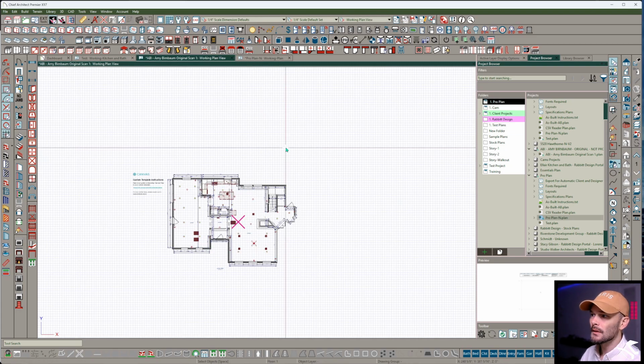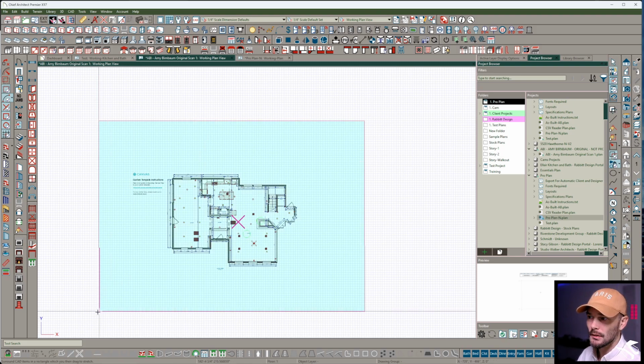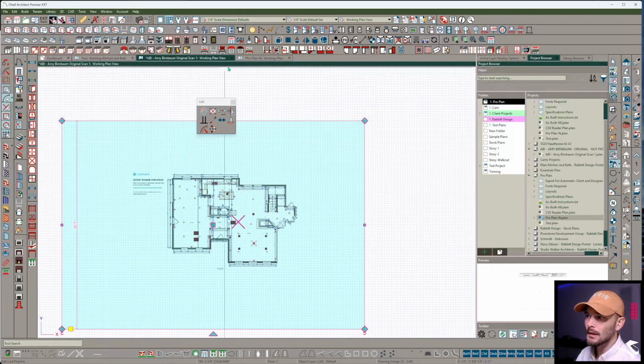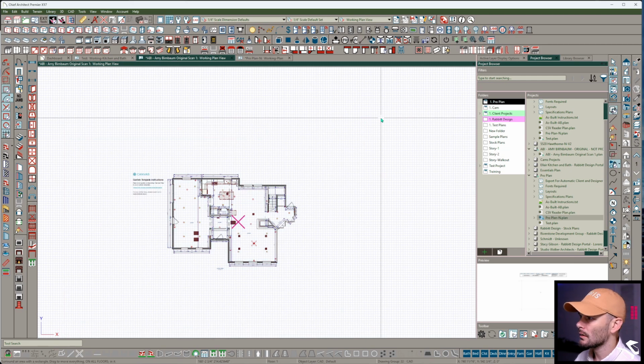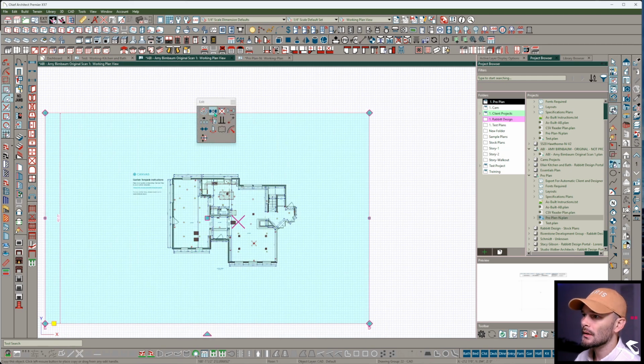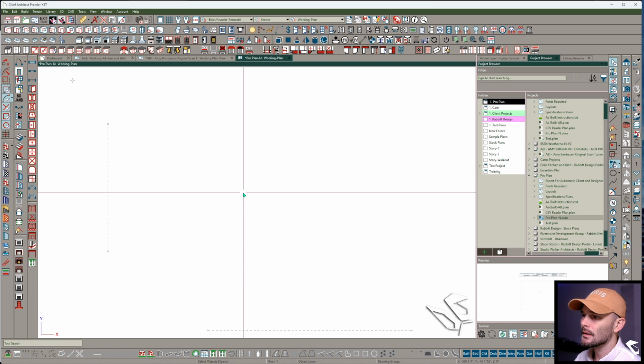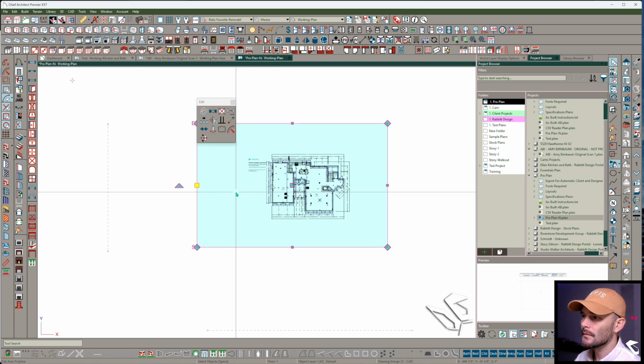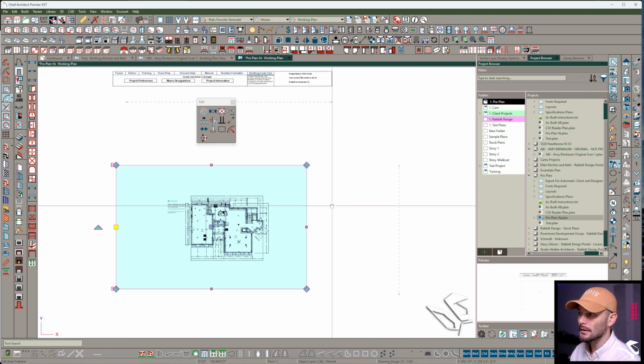Now, let's give this a shot again. I'm going to use that edit area tool, which is in the edit menu. I'll edit this, copy paste. Oops, let me try that again. Wrong tool. There we go. Copy paste, paste hold position. And notice there was no warning. That means we got our floor information correct.